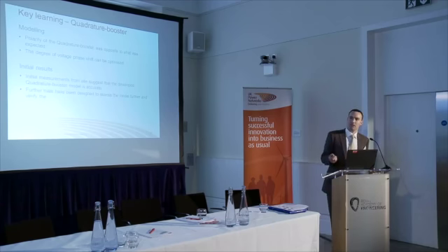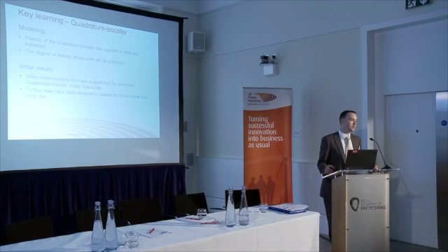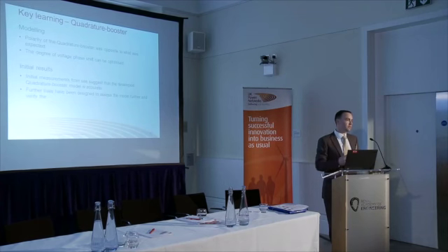One thing that maybe wasn't so clear from my graphs is that the optimal tap position is tap 11. With future deployments of quad boosters, we would look to have the optimum tap at, say, around tap 13 or so, which would give us a greater degree of control over the system. At the moment we have less control, which isn't an issue per se. We still get the additional capacity that we expected, and we're still proving the concept of the quad booster, but it's one of the key learning points we've identified for future deployments.